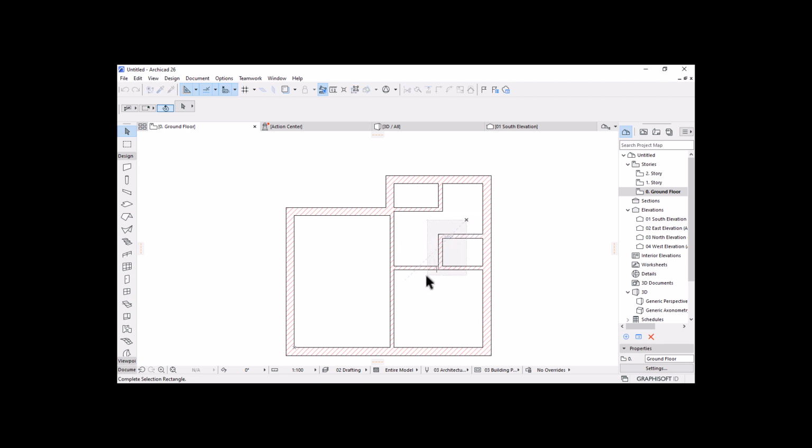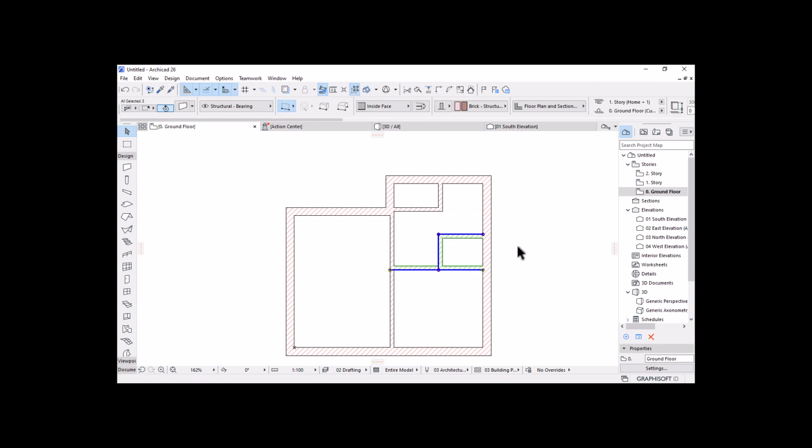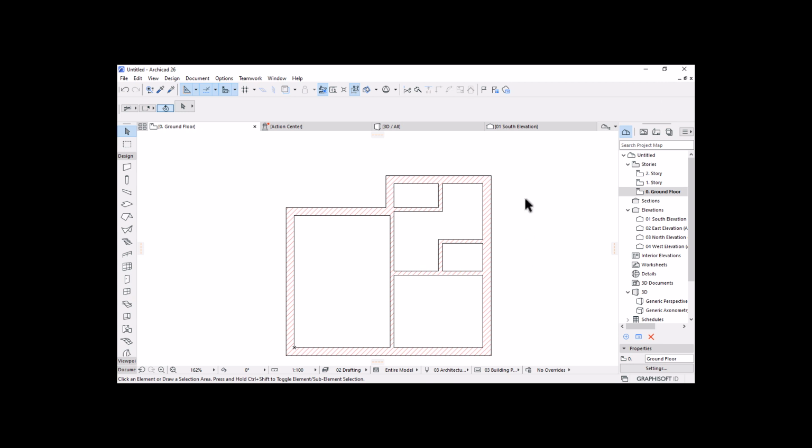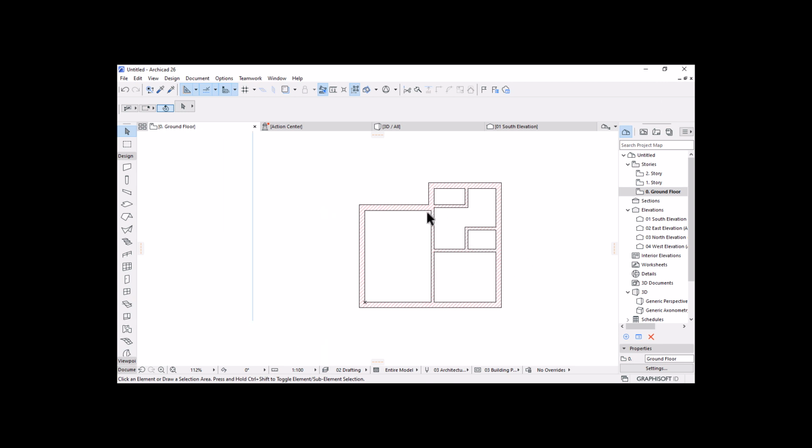Let's select all these walls like that, and then Control D on your keyboard to activate the drag or move command. And then I'm going to drag this by clicking the point outside here, and then go down vertically like that, and then I would add 140. Let's make it 200, right? Move by 200 to increase your circulation space. That's basically what we have there.